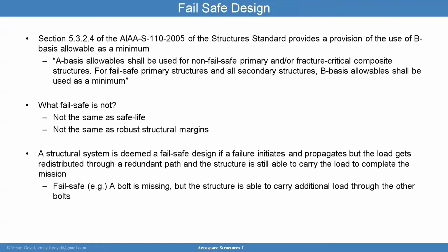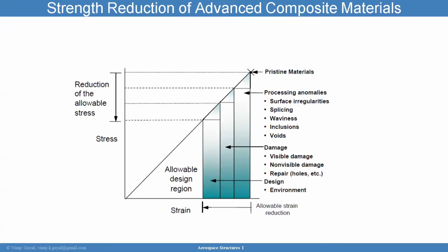And that is actually very valuable if you can incorporate it with very limited weight increase penalty. If you're able to impact your design by incorporating a fail-safe feature, go ahead and do that, because that's going to increase your confidence and it may decrease the amount of work you need to do for the verification of the structure as well. So there's a lot of value in implementing fail-safe designs while also limiting the impacts on weight. Very important considerations.